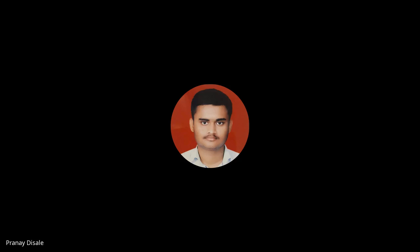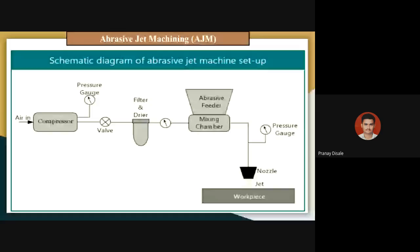That kinetic jet, that means the high velocity jet, you will get, and when it strikes the workpiece, this high velocity jet will erode the material. Erode means what? Erosion action. So due to that, the high velocity jet erodes material from the workpiece at a controlled rate, up to the desired shape or size whatever you want on the workpiece.